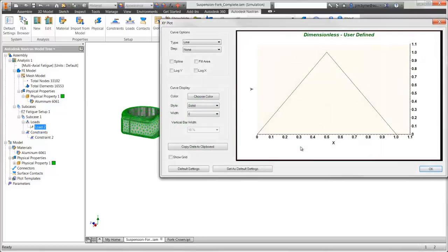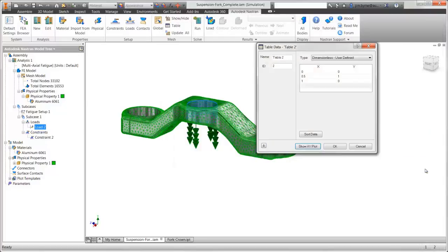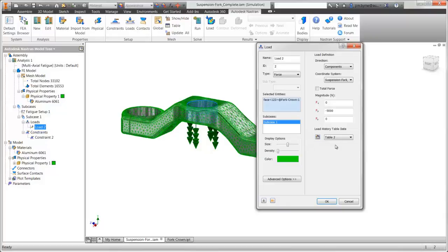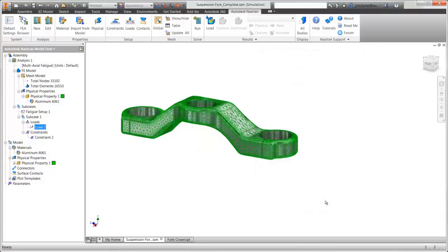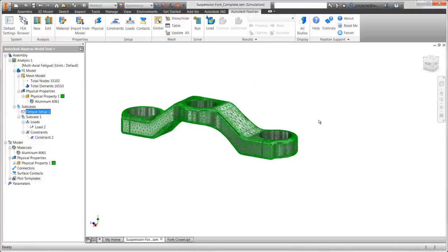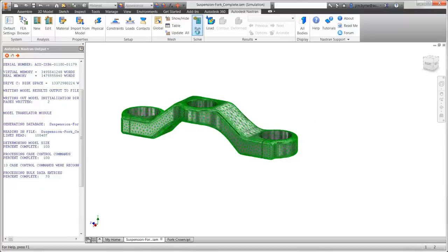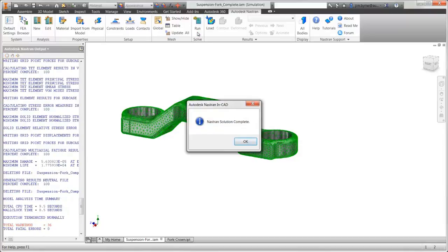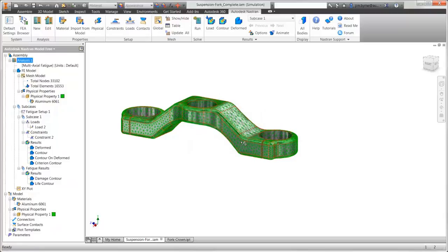After the values are applied, there is a chart to ensure they have been entered correctly. Finally, before we run the analysis, we'll specify the stress results from the linear static study to use between von Mises, principal, or shear. There are other settings available for how the results are displayed in terms of the number of cycles or time such as years to fatigue failure. The fatigue study results are calculated extremely fast. Almost all of the 20 seconds to solve are spent on the linear static results.